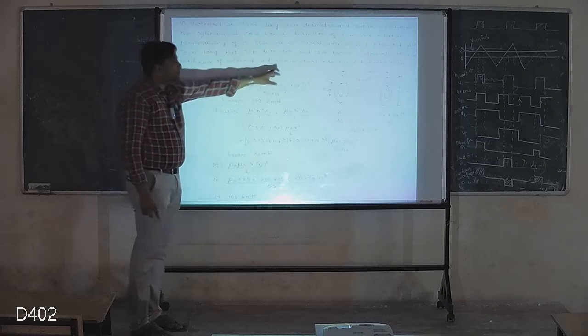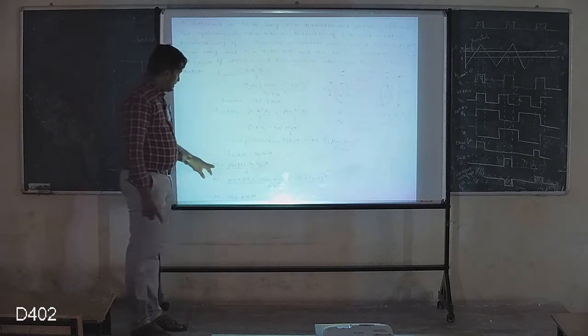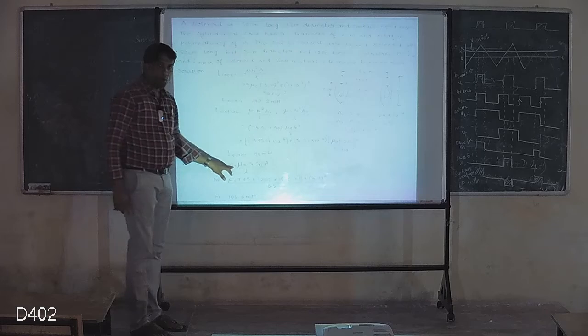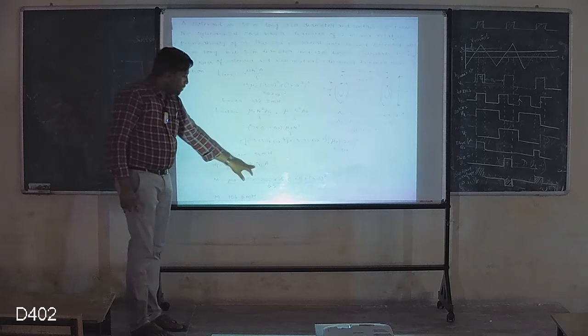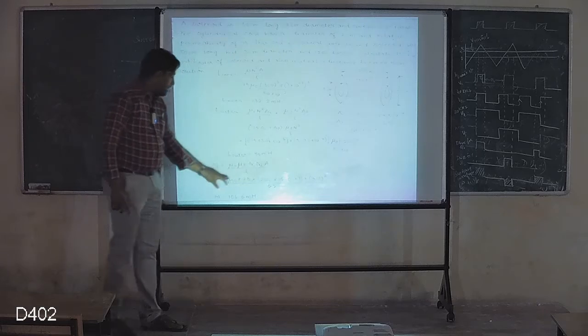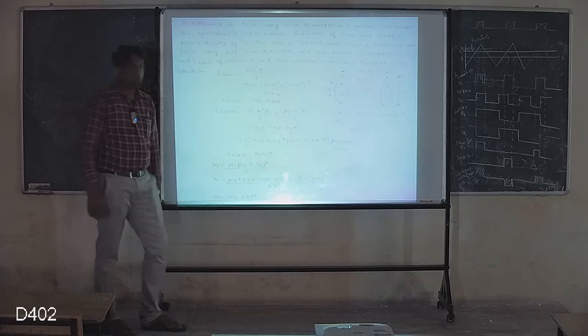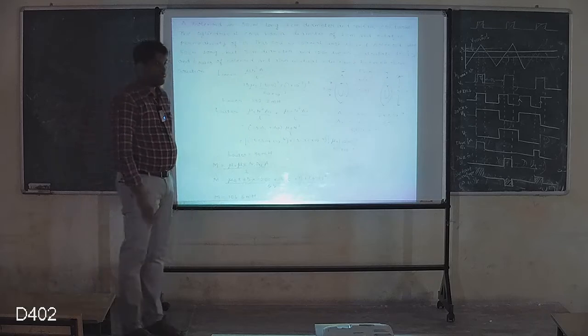And the problem still asks to find the mutual inductance. So M is equal to mu naught mu r N1 N2 A divided by L, which happens to be 106.6 millihenry.